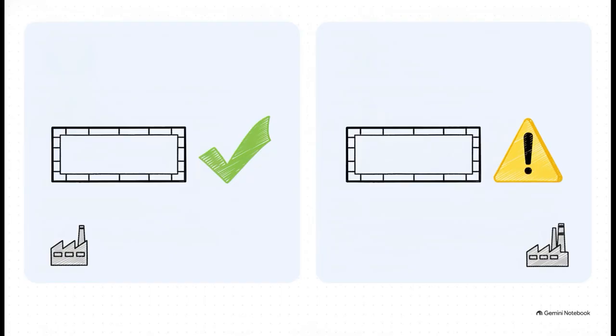So how does all this actually play out when you're reading a feature control frame? Well, when an American machinist reads an ASME feature control frame without any material modifiers, they correctly read it as RFS, regardless of feature size. But if that exact same frame shows up on an international print, that requires an immediate double check. ISO has a completely different library of modifiers and defaults. As a global supply chain engineer, you can never, ever assume defaults are universally interchangeable. A simple position callout means one thing in Detroit and potentially something completely different in Munich if the standards aren't strictly mapped out.